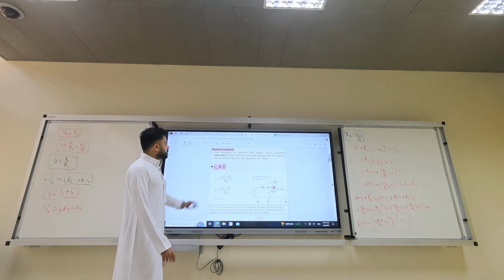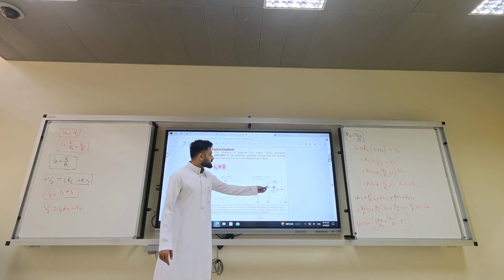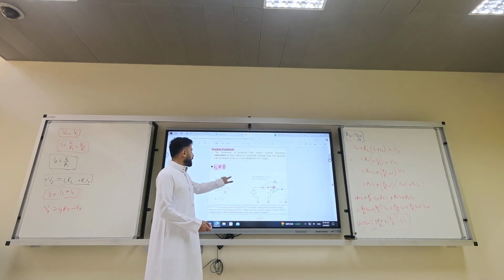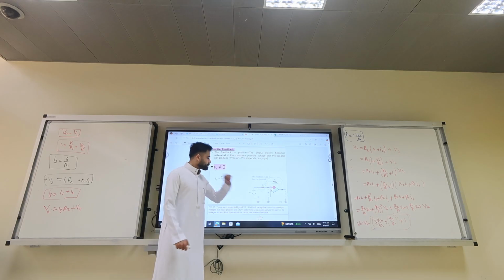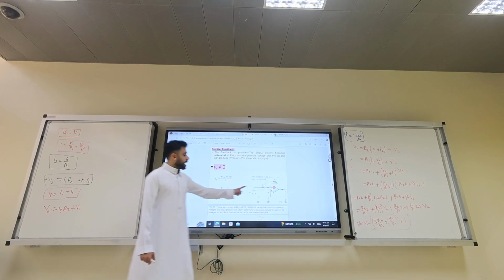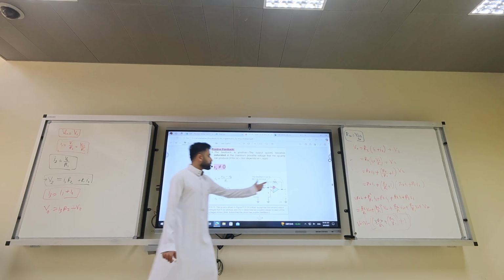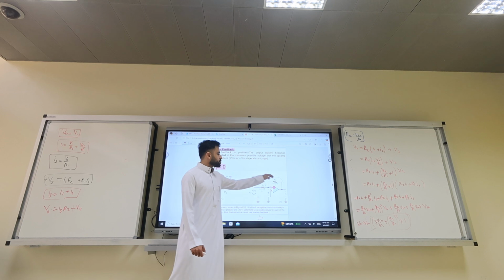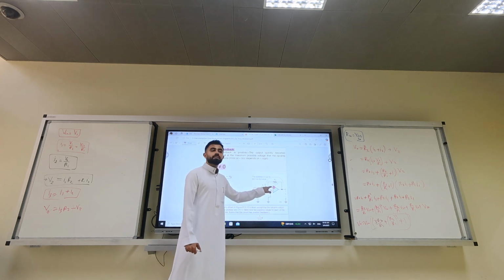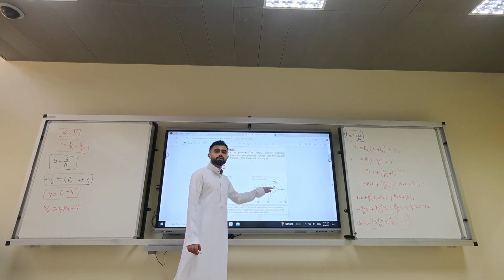Analyzing this circuit real quick, what is I input? It's V input minus Vx, or we call it Vi, I'm going to call it Vx to be consistent, over R1. I2 is what? Vx minus V output over R2. But I know that I1 equals I2. Still, all the op-amps cannot allow any current to flow inside their input.